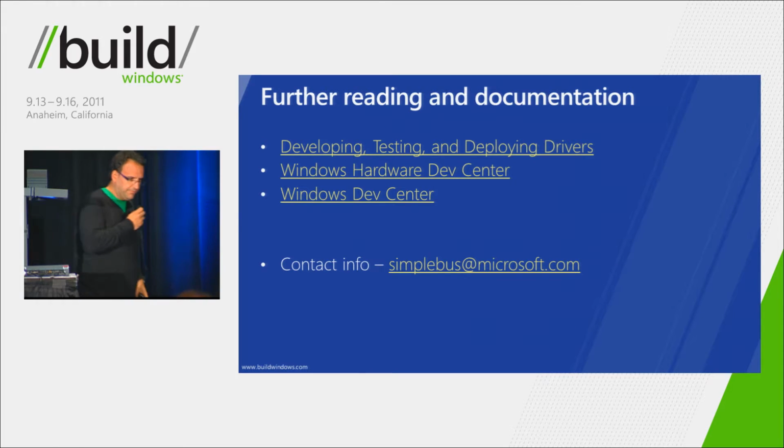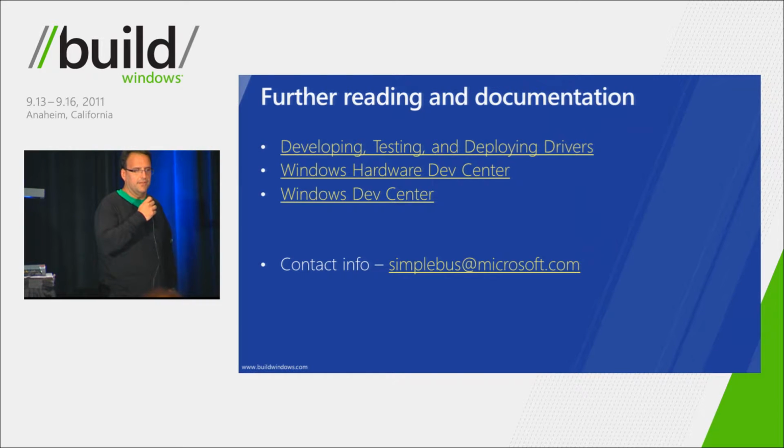For UMDF, I don't like to call it a penalty, but there is a cost associated with isolation. 1 millisecond is probably at the edge where you want to do some performance testing and prototyping and see what you can actually pull off. And on the SPI question, I just wanted one quick clarification: we do support shared devices, but it's a single master architecture. We don't support multi-master in this release.